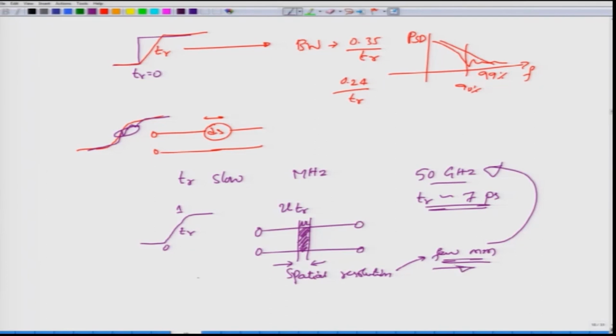So which means any discontinuity which is just about a few millimeters will be able to be resolved. Okay, the corresponding capacitances and inductances that you can measure are very small. In fact, you can measure capacitances of a few femtofarad, which is certainly not possible with traditional LCR meters. Okay, traditional LCR meters cannot measure such very low capacitances, whereas a TDR can easily do that and in fact display nicely the corresponding graphs to you. Okay, so a catalog of TDR scopes is available on the internet.